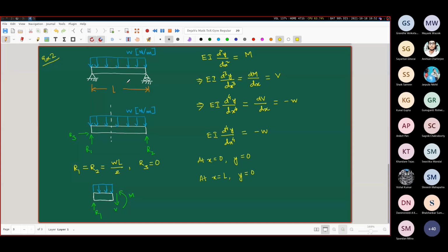So you need some kind of foolproof method of writing down the conditions in terms of the overall given structure, instead of trying to cleverly exploit the symmetry, because in many situations the symmetry is just not going to be present. So tell me, from a more fundamental consideration, just by looking at the supports, what the other conditions will be. You all know the answer. The moments are zero. Yes, very good. The moments are going to be 0.